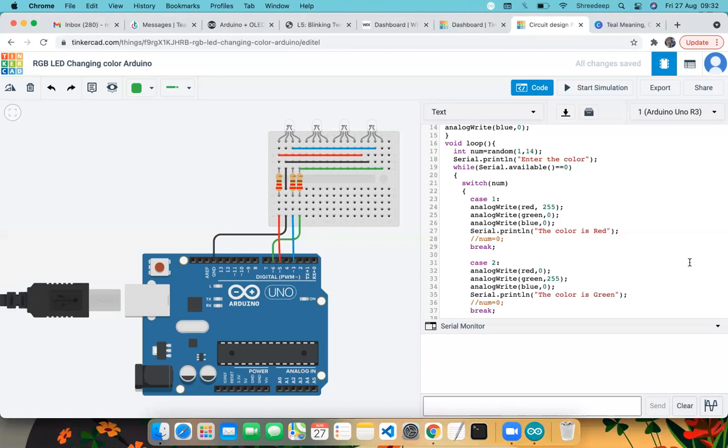So you are just moving up and down across this menu to see what colors are available in this project. Let's say you have 10 colors available on the screen. You are moving up and down, and finally you select: I want to showcase yellow. The moment you stop and press the button, that means you have selected the yellow color. That is the usefulness of the rotary encoder. You have a menu-driven interface, a switch acting as an enter button, and at the same time up arrow and down arrow key facilities just by rotating the knob clockwise and counterclockwise.